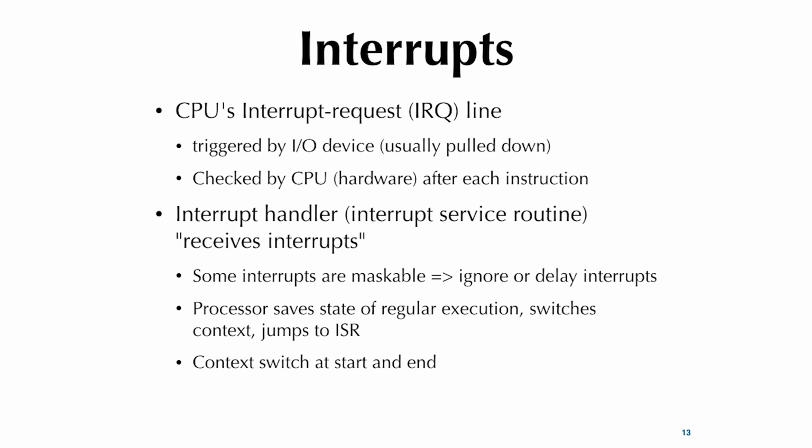And so when that line is asserted, the processor sees it, and the processor has hardware to check. Then at an instruction boundary, at the first opportunity, it flushes the pipeline and jumps to the interrupt service routine, as long as that interrupt is not masked. Remember, you have that EA bit, right? The EA bit can mask or temporarily prevent these requests from coming in.